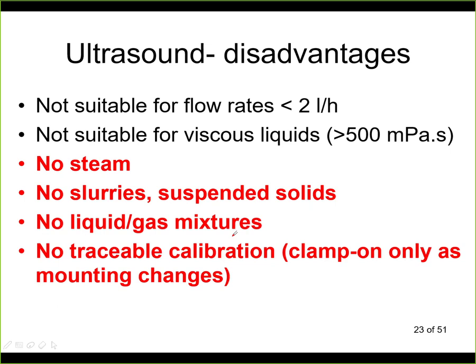It does not have a traceable calibration. This applies for the clamp-on system because the mounting will change, and if you want to have traceable calibration, then you need to have the inline system.